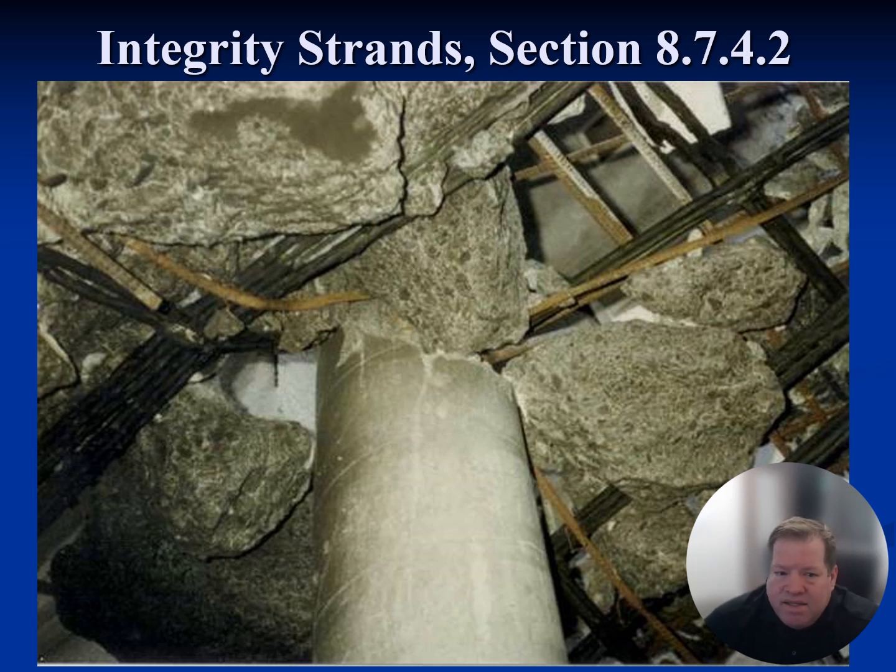This acts as a big safety net, catenary action, a big spider web, and just holds this thing together. Now, obviously this thing took a beating. It's going to get demoed, or it did get demoed and rebuilt, but it didn't come down. The continuous reinforcement embedded in those columns allowed for load distribution and just for the thing to hang on.